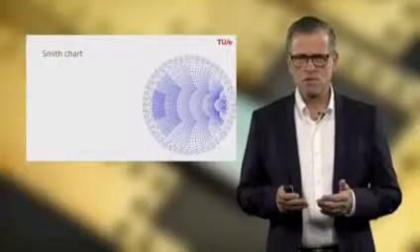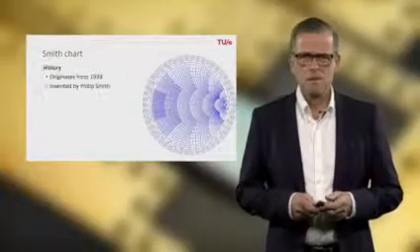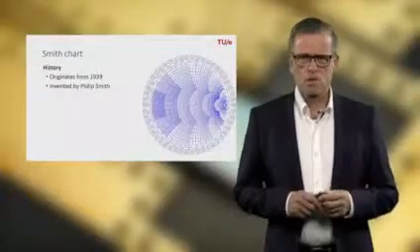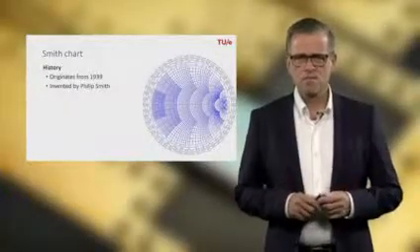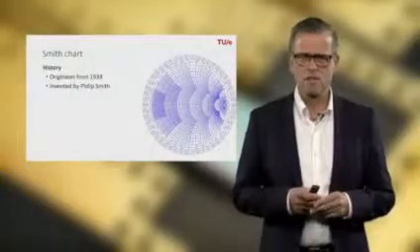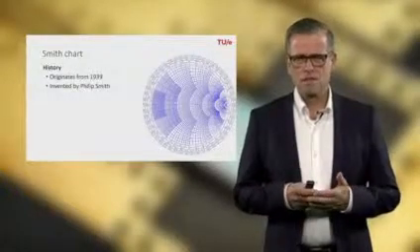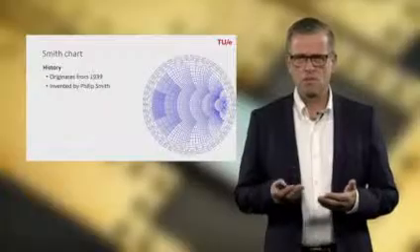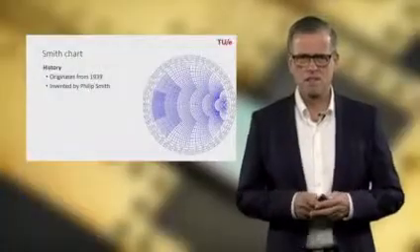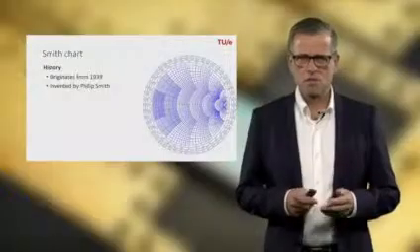It consists of many circles, curves which are part of circles, and many numbers on the Smith chart. Now it originates from the period during the Second World War, so it's in fact 80 years old already, and in that period there were no computers, so it was very useful to have a tool to plot the complex reflection coefficient and to transform that directly to complex impedances, complex admittances, VSWR, etc. Philip Smith invented the Smith chart, which is the result that we are going to discuss today.